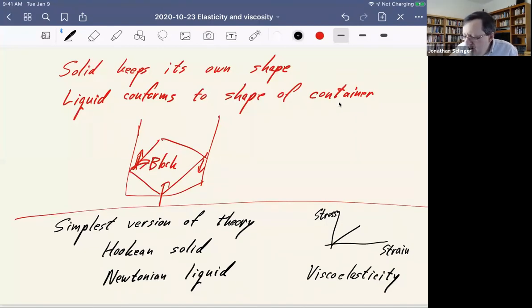And there is a shear modulus G of omega that depends on frequency, which is a lot like the impedance that depends on frequency in an AC circuit. It also is a complex number, the same way that impedance is a complex number for an AC electrical circuit. And then there are other complicated aspects about tensors, about relative directions of forces and displacements, which is a further sort of issue that people can study.